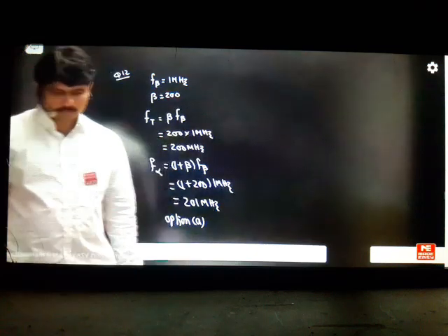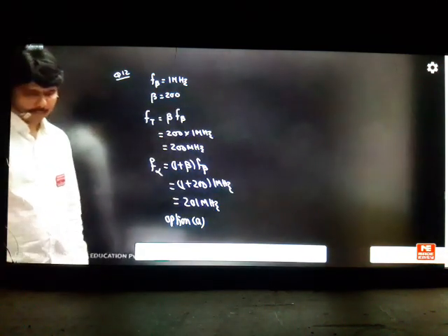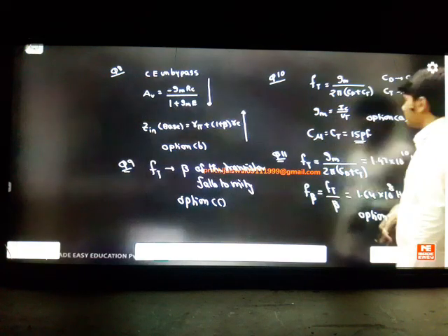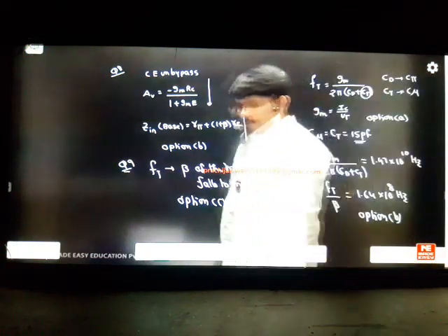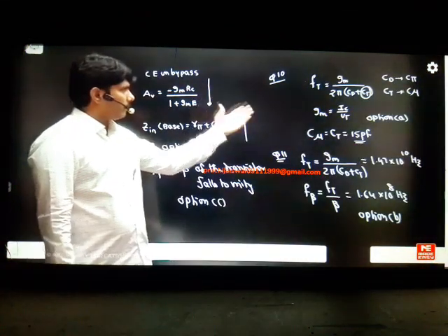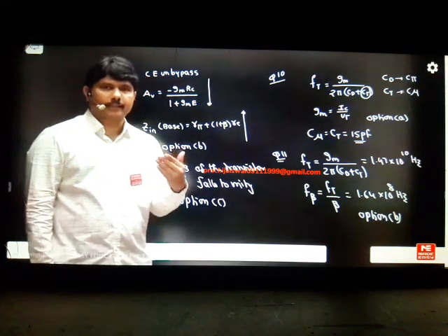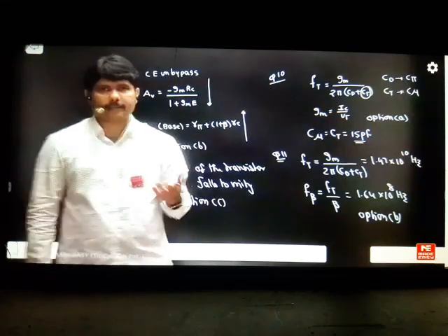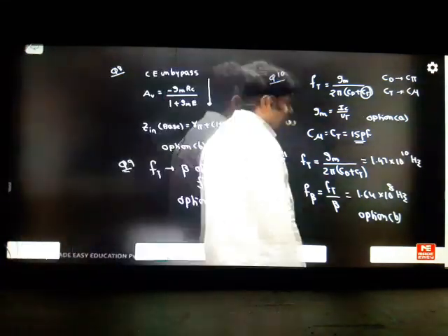What did we do in question number 10? We applied the formula, this is unknown, and I am solving this answer. The formula we know: CT is nothing but C mu. That indicates CT is C mu. I am solving C mu with the other parameters he has given. But he has given IC, so first calculate GM, IC by VT. Then solve it. Nothing more than that.